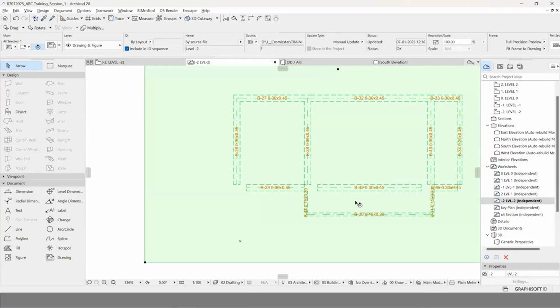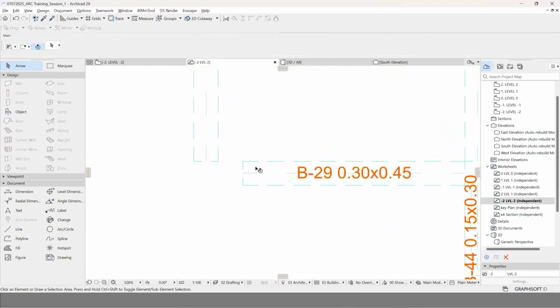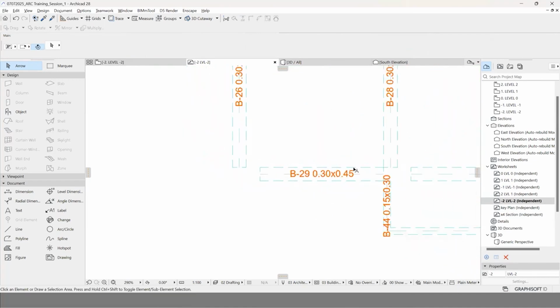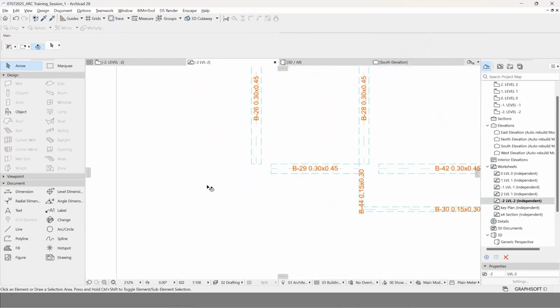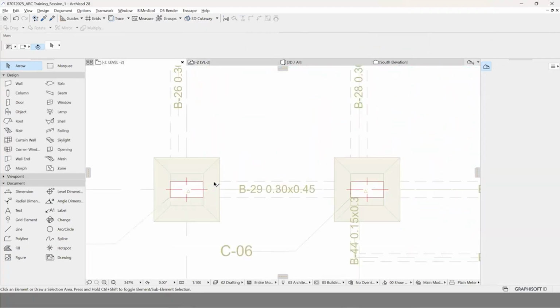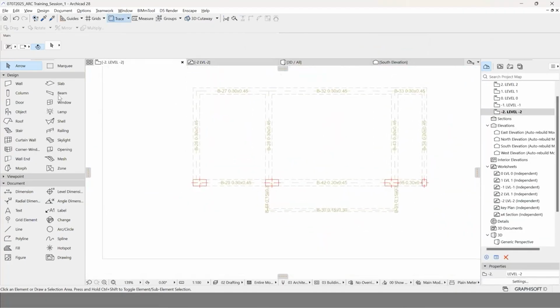So like this, now you can filter. So let's say you have all the projects and everything is there. Now you can filter it in this way and you can work. And one advantage is you can snap to these points, even though these are not lines at this point in this particular drawing. So here also you will see the same. So now it is very simple for you to snap to those locations and work.